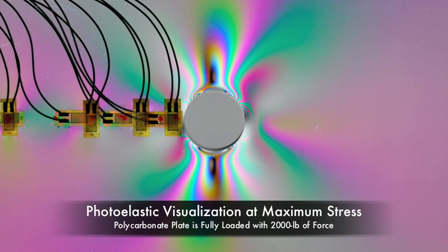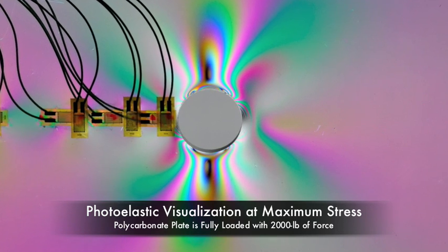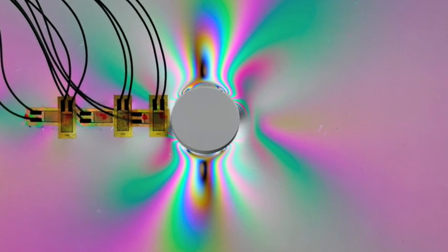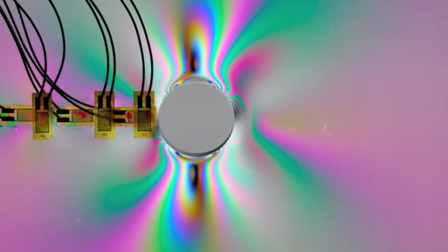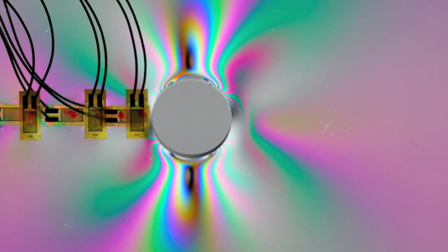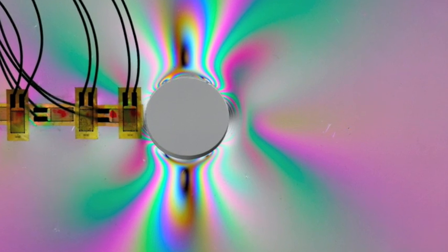Denser contour lines indicate higher values of stress. On the HH line, the contour lines are most densely packed at the edge of the hole. As the distance from the hole increases, the stress distribution becomes more uniform. This matches our finite element analysis simulation shown earlier.